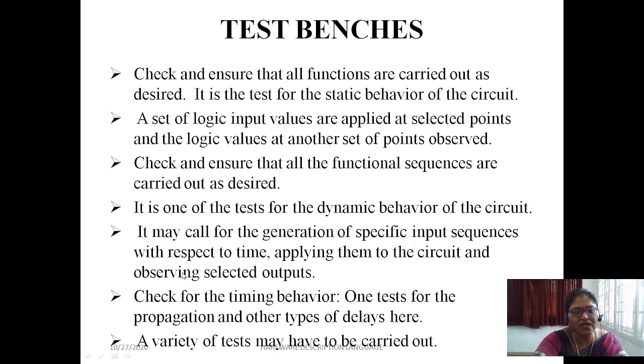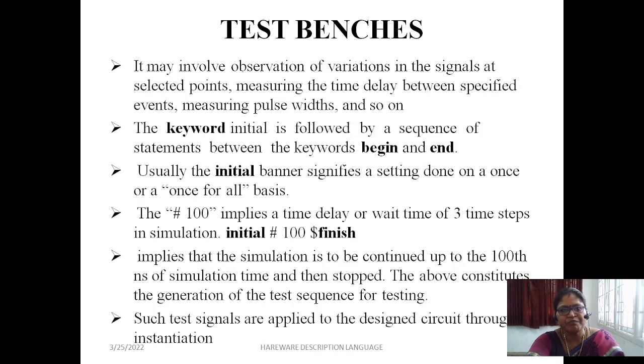Here is one test for the dynamic behavior of your circuit using test benches, checking the timing behavior, and testing for propagation and other types of delays. So a variety of tests may be carried out here. It may involve the observation of variation of signals at selected points, the time delay between specified events, pulse width, and so on.